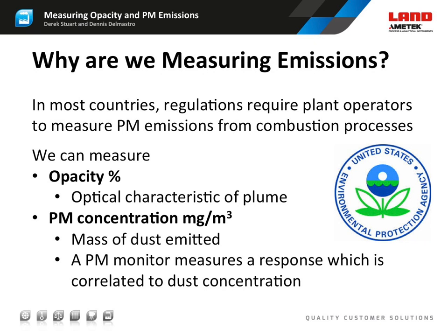Since regulatory actions are why emitters have to measure emissions, the regulatory requirements are usually to measure either opacity on a percentage basis or PM concentration on a milligram per cubic meter basis. You might note that opacity is actually just an optical characteristic of the plume itself, while PM measures a response, which is then correlated to dust concentration.